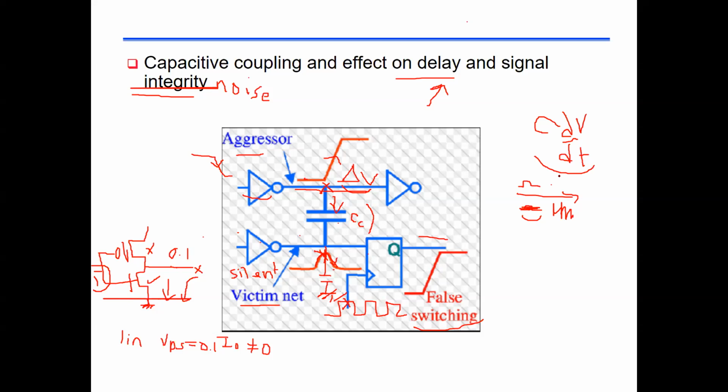So the total capacitance, as a relative quantity, its effect on the expected delay is going to be bigger, because the total wires are getting longer, and the wire capacitance is bigger than the gate capacitance. As we scale, we are shrinking some capacitance and increasing some because we are making longer wires, but the importance of the interconnect capacitance is significant and we need to take it into account in my overall delay. Right, as you say, if it kept growing while I shrink the chip and the transistor, I would not have been able to increase the frequency.